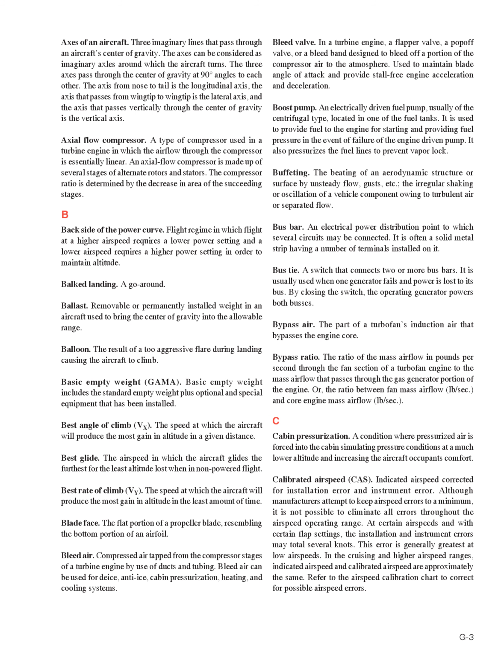In a turbine engine, a flapper valve, a pop-up valve, or a bleed band designed to bleed off a portion of the compressor air to the atmosphere. Used to maintain blade angle of attack and provide stall-free engine acceleration and deceleration.